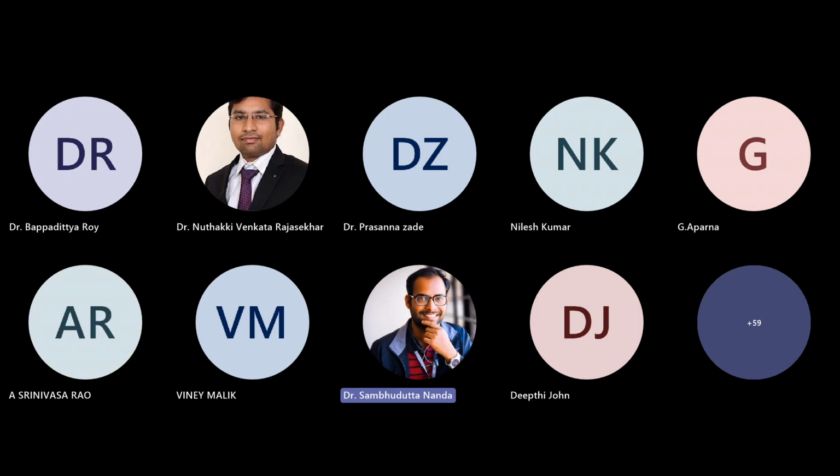Can you please ask again? What should be the procedure to get the 2D radiation pattern? 2D, 3D is very easy. For the 2D radiation pattern, sir, it is there already. Azimuthal plane or elevation plane, you have to select. It will give you the E plane, only the E plane for that, not the H plane. Okay, only E in MATLAB. Yes. Okay, yes, sir.